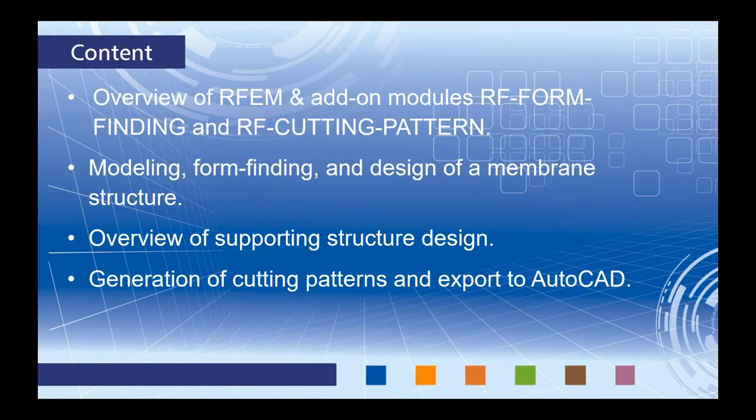So as far as the content for today's webinar, I want to give you a brief overview of RFEM and in particular the add-on modules RF form finding and RF cutting patterns for tensile type structures. Then we'll move on to a specific example in RFEM, including modeling, form finding, and the design of a membrane structure. We'll touch on the overview of the supporting structural design, including AISC design code checks. And lastly, we will generate the cutting patterns of the membrane elements and export these to AutoCAD.